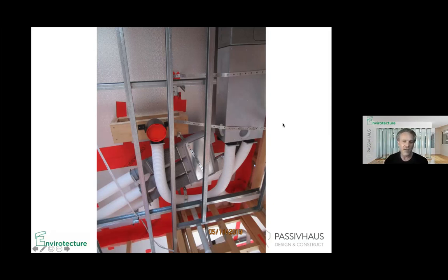Whereas here, because every one is unique, you can adjust and tweak each of the outlets, which are not in this image, but that go where that red cap is, and therefore you can adjust the airflows quite accurately. And that's the commissioning process as part of the certification, because you want to make sure it's actually going to work, which again sounds obvious, but for the inexperienced is quite easy to get a bit wrong. So that's the sort of the construction part. The rest of it is just building a house.